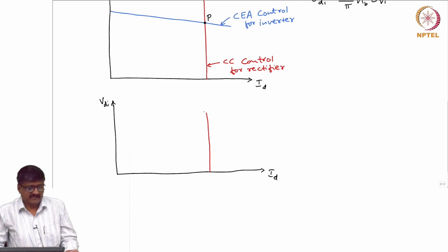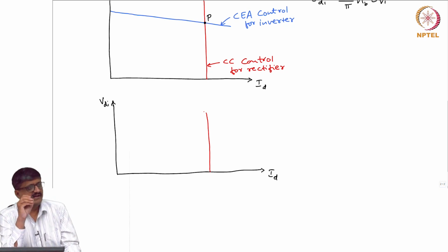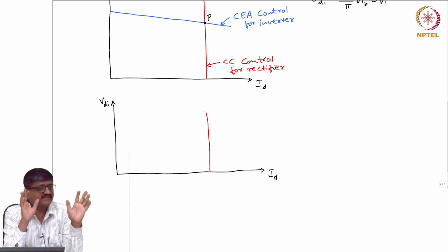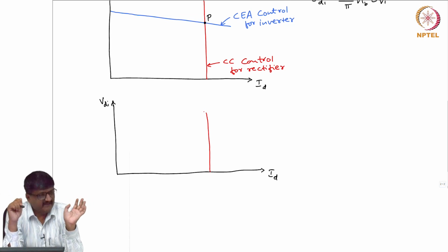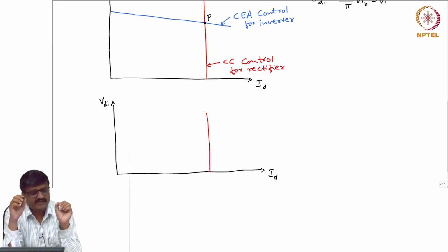Yeah, suppose the supply voltage is constant, the AC side voltage is constant for the time being, and we just consider the fast controls. Okay, so forget about the slow controls. Assume them to be constants, and even the other voltages to be constant. The AC side voltages are constant. Tap ratios are constant, the off nominal tap ratios. Then how do we get the other end?